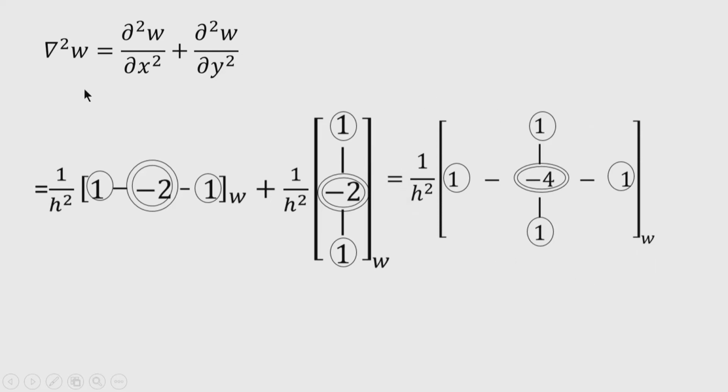Okay. Now, it is possible for us to find out the finite difference form of the plate equation. How can we form it? Because we know the Laplacian operator. So, the finite difference form of the plate equation is found by writing del 4 w equal to del square into del square w. Okay.